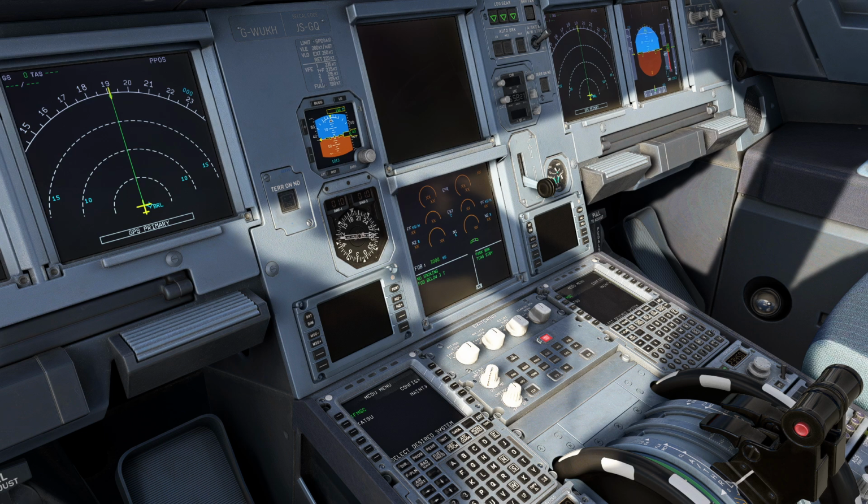When I release the button, again engine warning display replaces the system display, as a concept designed by Airbus. Push and hold for a maximum of 3 minutes the related system page push button on the ECAM control panel to temporarily display it on the lower ECAM DU instead of engine warning display, as we checked already.